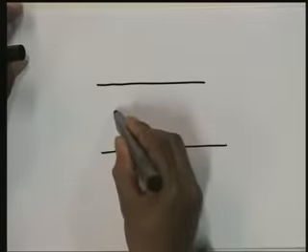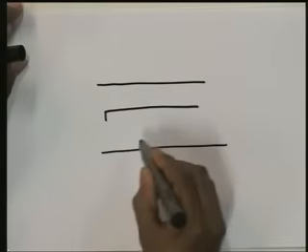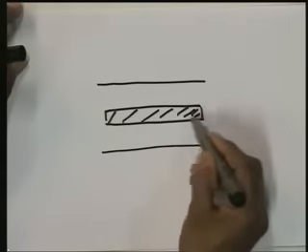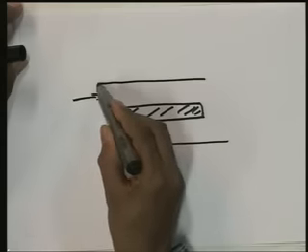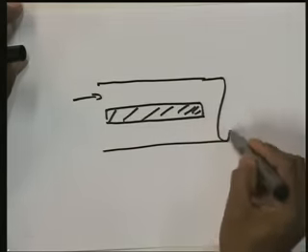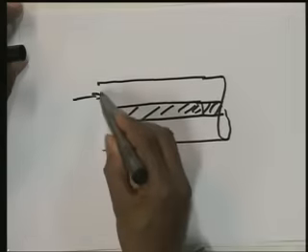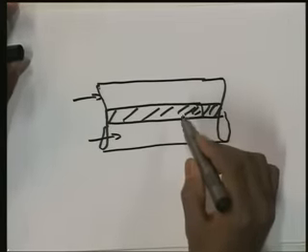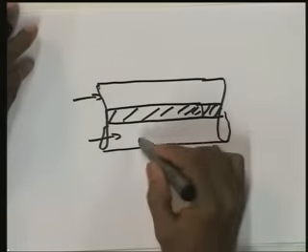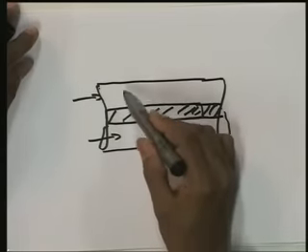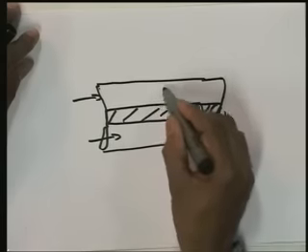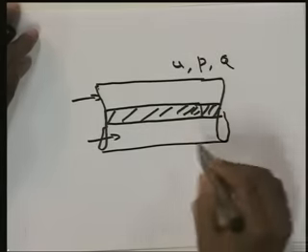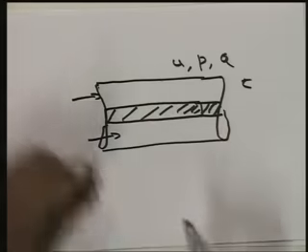Here the flow is between two sections like this. So, you can see the flow is between one central axial cylinder and the pipe, in the space between it and another pipe. So, we want to find out here the velocity variation, the pressure variation or the discharge and shear stress and all other parameters in the case of annulus.